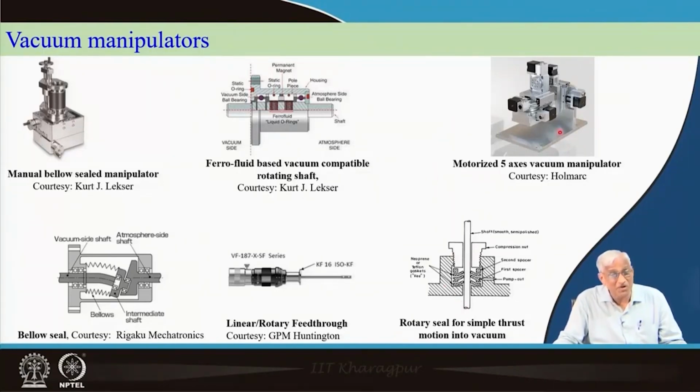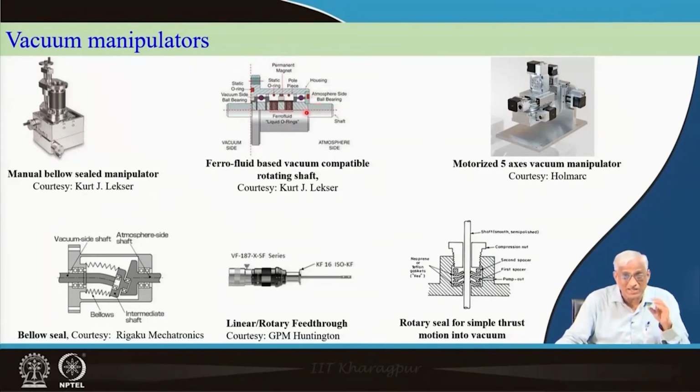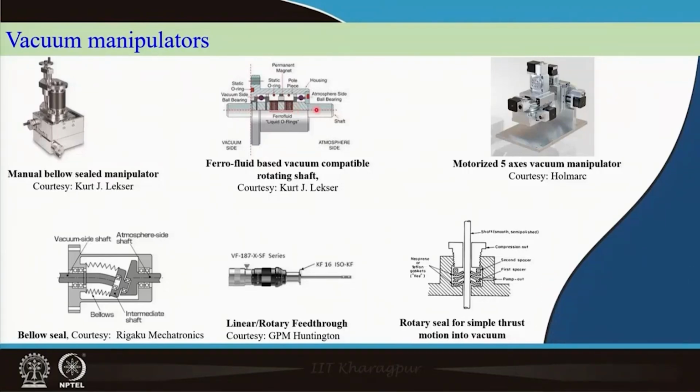But today we have very specialized shaft seals like ferrofluidic seals. There is a ferrofluid, a fluid with suspended magnetic particles, they will form a magnetic circuit, and in the process by making certain elements magnetic, and while it is rotating, the fluid property is used to stick to the shaft tightly like a shaft seal.